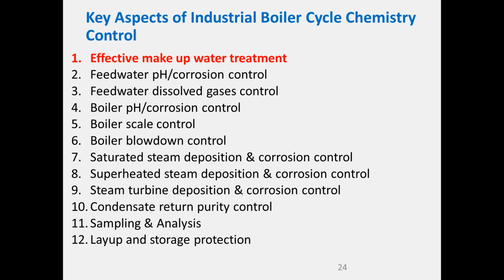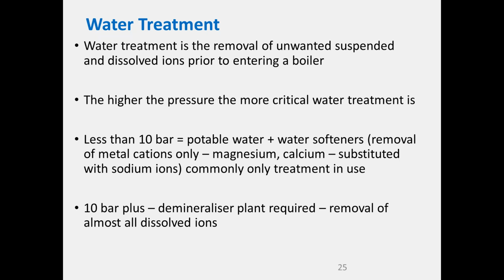So first one, effective makeup water treatment. Water treatment is the removal of unwanted suspended and dissolved ions prior to entering a boiler. So if we took the lovely Waikato river water and we put that straight into a boiler, it's got both suspended material, maybe the odd swimmer and things like that still in there, and a whole lot of dissolved material. And as we start to heat that up, we change the solubilities, and we'll get an awful lot of deposition, and the water may actually be quite corrosive as well. The higher the pressure of the boiler, the more critical the water treatment is.